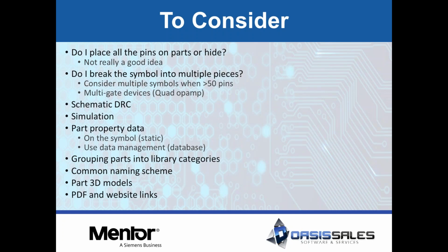It's going to get unwieldy after a while and make it hard to find items. Create folders or libraries based on major categories of components, like capacitors, resistors. You can even break up caps into two categories: polarity-based ones and non-polarity-based ones. ICs could be broken up into multiple categories, even depending on how many devices you're using currently at your company. So consider that when you're creating your library content, and I'll show that a little bit with my Essential Library, how we broke that up as well.